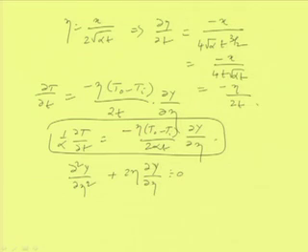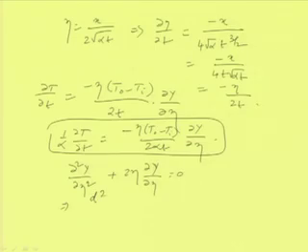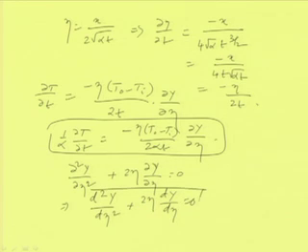So, it is only one variable. In that case, we will write del y by del eta as a perfect differential in place of writing it as a partial differential. So, we can write now d 2 y by d eta 2 plus twice eta dy by d eta equals to 0. So, this is the reduced governing equation for the present case.